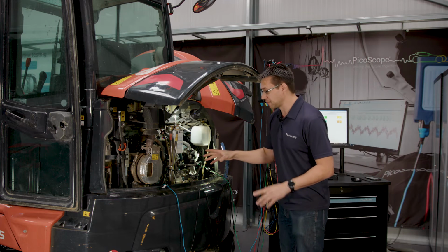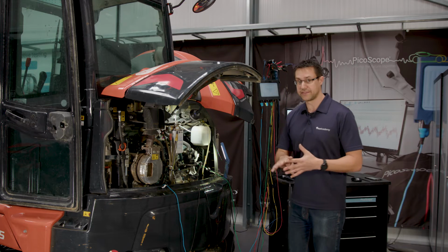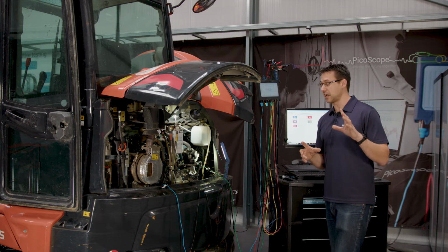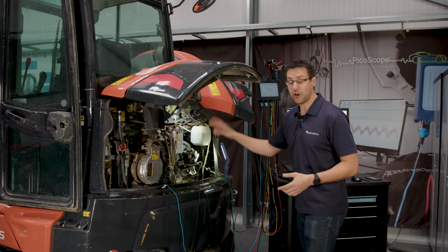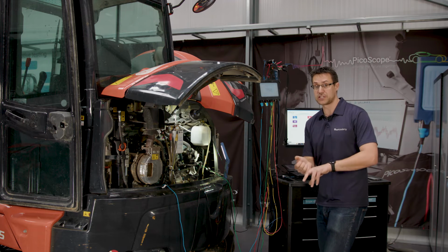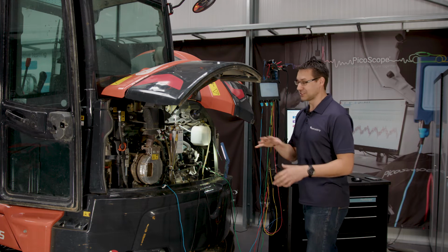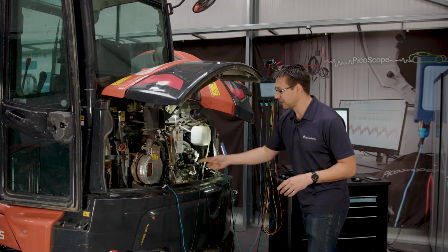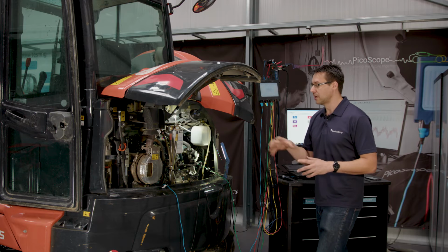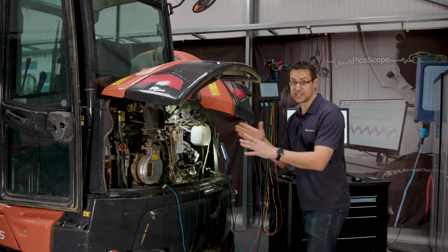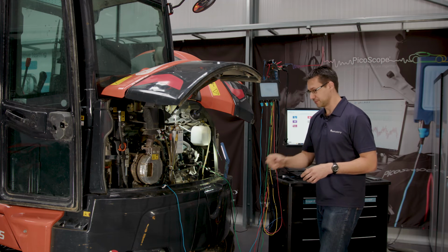So, other captures that we've already set up for. I've got the crankshaft sensor on channel A. I have a cylinder identifier. Now that can be a number of different ways. In one of the guided tests, I think we're using the current clamp on the injector. If you can't get to the injector, camshaft sensor is another good one. If you can get to a camshaft sensor, great. If you can't get one of those, start to think slightly outside the box and maybe look at vibration from an injector pipe. You know, there's all sorts of different ways that we can try and determine how the engine is determining where it is in its 720 degrees cycle, so you can start to identify individual cylinders.